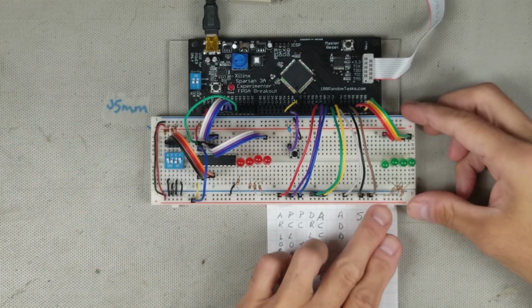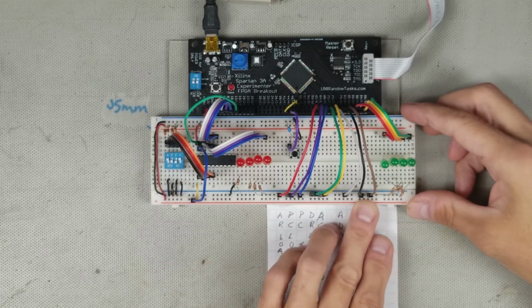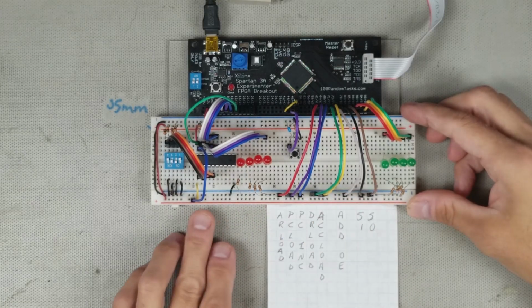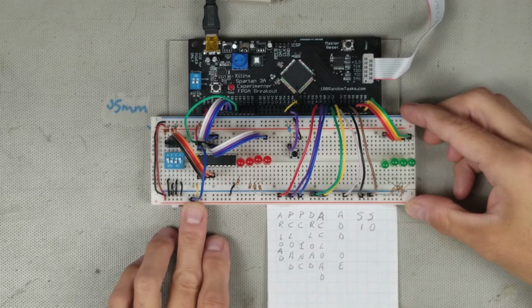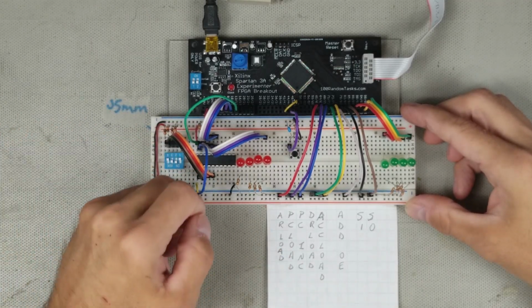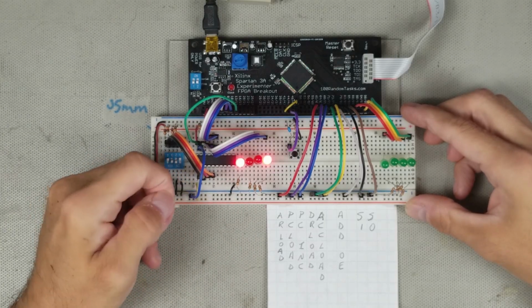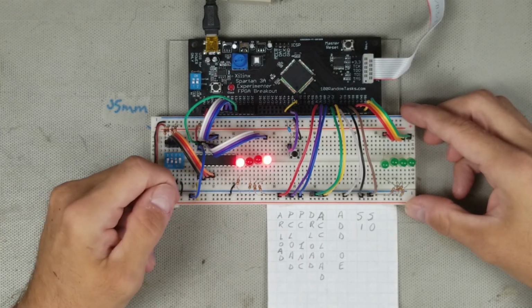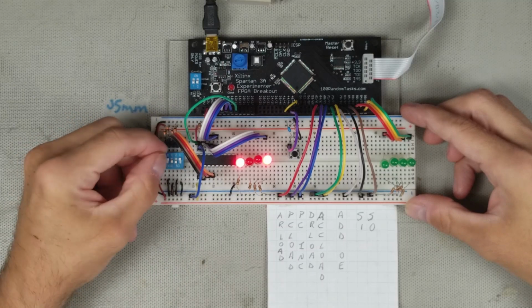Right now all the control lines are low. The select lines are 0, 0, so this points to the accumulator, and the read-write line is high, putting what's on the accumulator onto the memory bus and disabling the 245 buffer. If I switch it to read, it shows 1001, which is what the dip switches are set to. If I flip one of the switches, you see the value change.